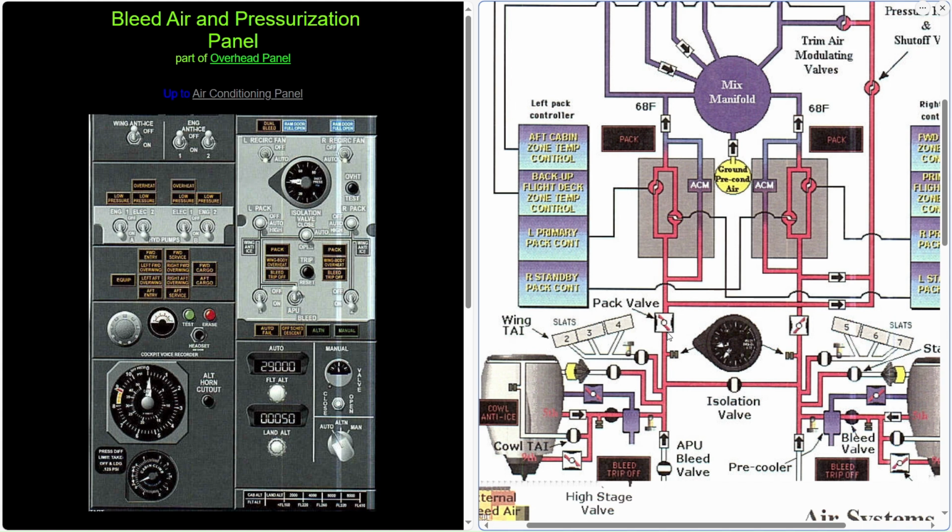And then we have the pack valve, which you can see right here. This pack valve is over on the right pack here, and it's off, auto, and high. Auto is whichever pressure you need, either fifth or sixth, whatever it needs to keep the system going. And then you see high. High is the ninth stage, because you need more pressure. So that's going to pull the pressure from the ninth and not mix the ninth with the fifth.